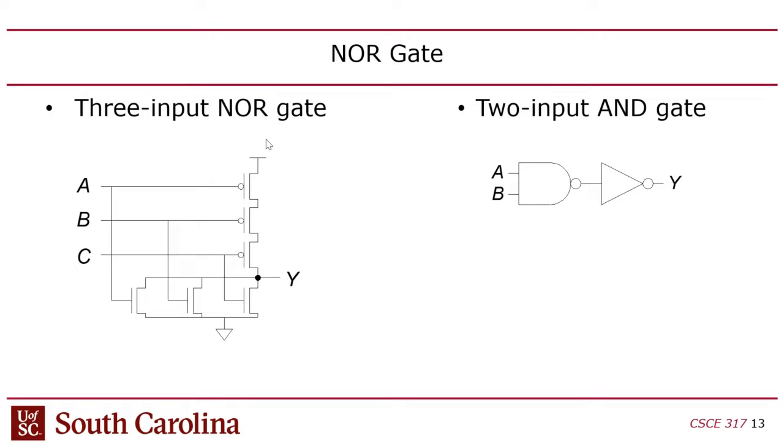But if you have a gate like a 2 or 3 input gate, like this 3 input gate, what happens if I set all 3 inputs to 1 all at the same time? Well, that's going to create 3 parallel connections to ground, right? As compared to switching only one of these inputs to 1 and leaving the other 2 at 0. If I do that, I'm only going to turn on one nMOS. So the question is, is this gate going to be faster if I set all inputs to 0 at the same time versus just have all inputs be 0 and, sorry, let me repeat that.